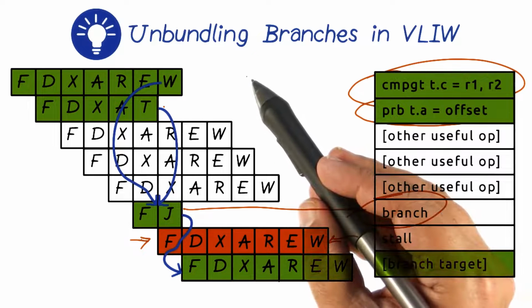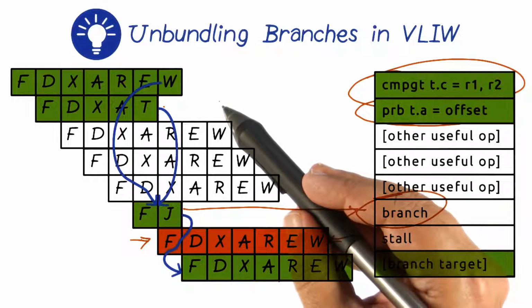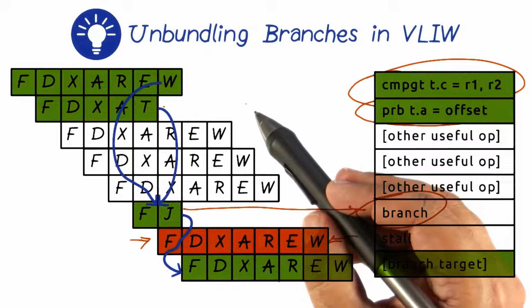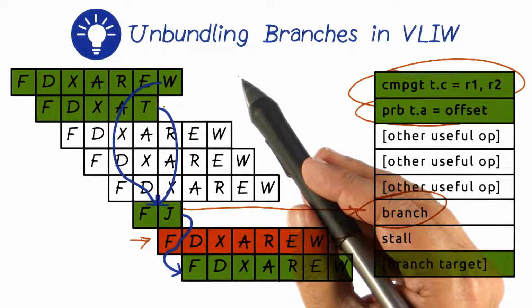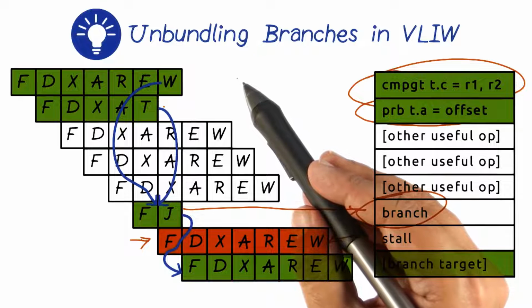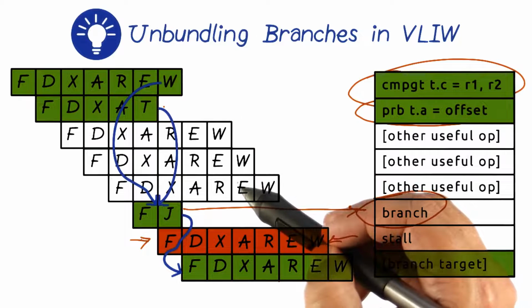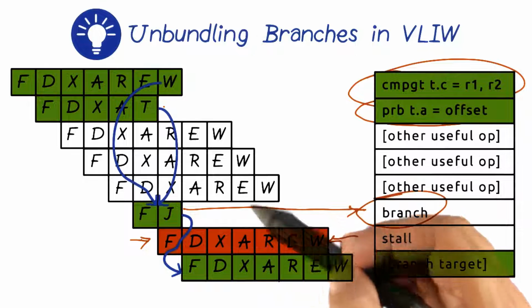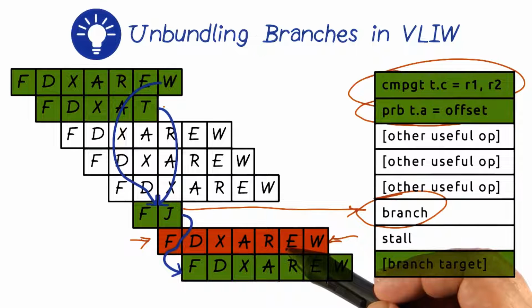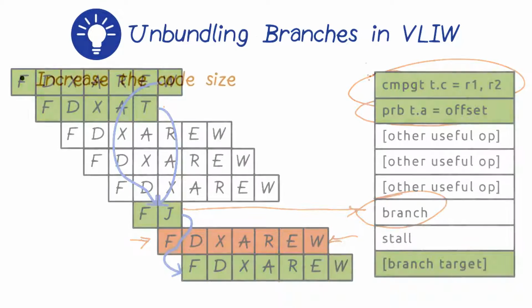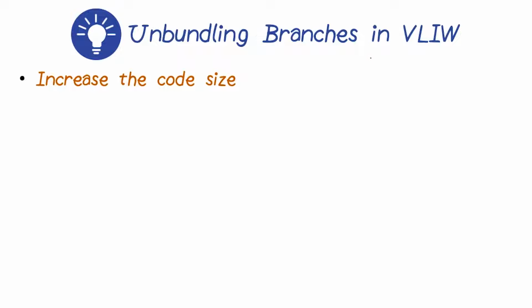So you can see that the goals of optimizations are keep the branch target ready or the PC address ready, and keep the condition ready to select the right target, and then start processing and fetching those instructions, and therefore minimize the delays once the branch actually jumps. So you may wonder that if this is the case, 2-step and 3-step branching should be very commonplace and is an obvious solution to the latency and the delay problem in terms of branches, especially in VLIWs.